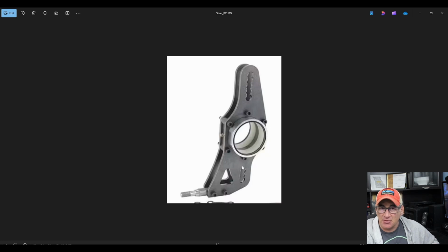Sometimes we refer to that as the pinion climbing the ring gear in the rear axle assembly. So something has to counteract that force, and in a coupled rear suspension, all that axle rotation gets reacted through the links that are solidly welded, or the brackets that are welded onto the housing of the axle. And then the links actually counteract that rotational force.